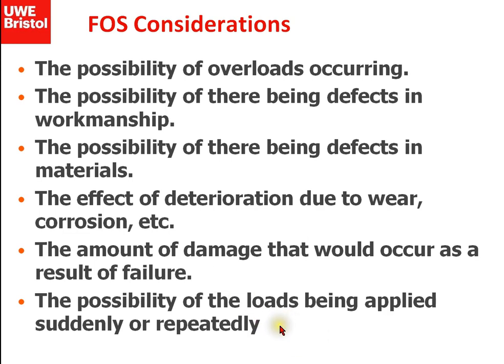And then there's this issue of fatigue. We are assuming that stresses are being applied slowly and not repeatedly. If we suddenly apply the stress, there's going to be an associated acceleration, so an associated impulse or force, which would mean we get higher forces being applied than we expect, and a repeated application of force can lead to fatigue issues.